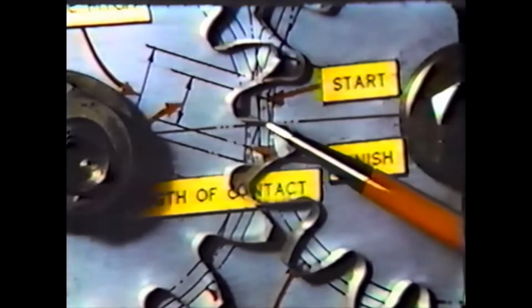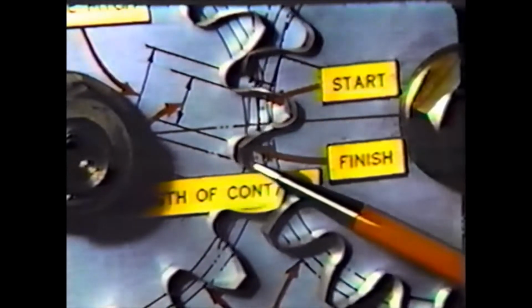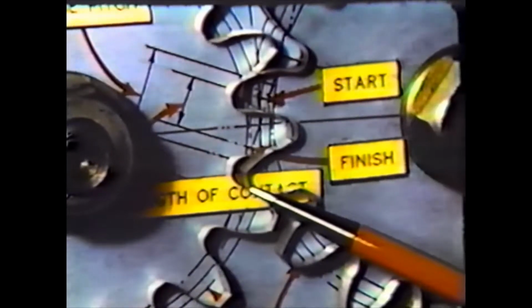As these gears are rotated, observe the points where the teeth start contact and where contact ceases. In properly designed gears, the line of contact should be of sufficient length to ensure continuous action. This pair of gears meets this requirement.